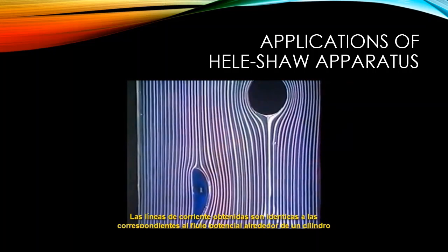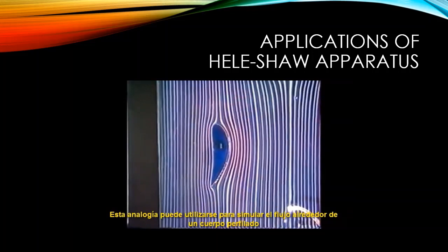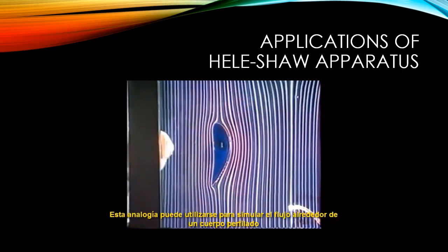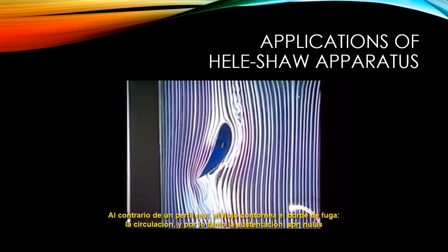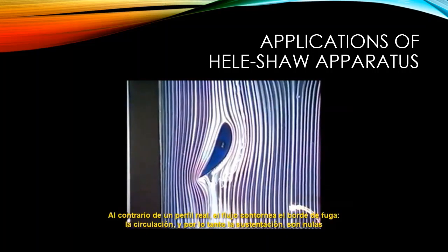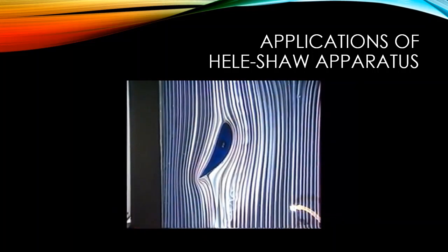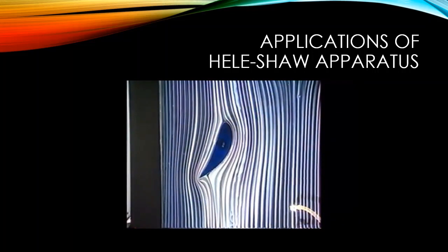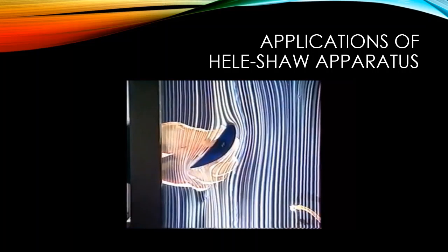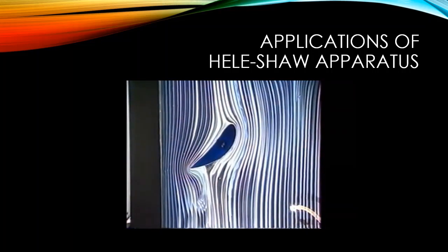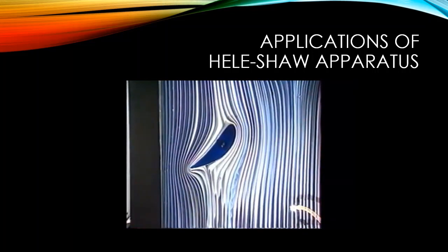And similarly in the bottom we have the airfoil model at 0 degree angle of attack. This is an unsymmetrical aerofoil, and I am going to increase the angle of attack. When you increase the angle of attack, the flow gets deviated from its path. You may see that we have boundary layer separation at the trailing edge corner, and also a vortex at the beginning, and then we find the reattachment region very quickly. When I increase the angle of attack further, we will have the reattachment point where the boundary separation occurs.